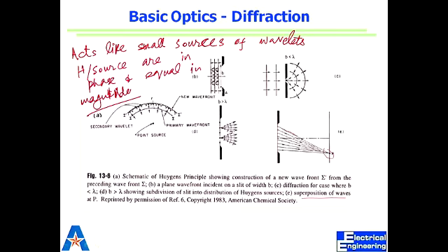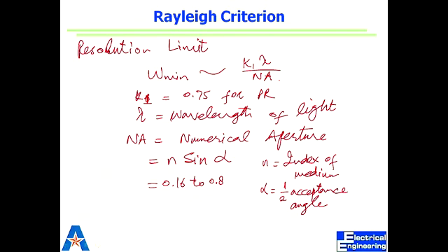The idea is that this results in specific relations that depend on the numerical aperture of the medium, because of those point sources of light. We have seen this before, right? The resolution limit, the smallest feature that can be made with the technology, depends on K1, which is a constant for a specific photoresist, the numerical aperture, and lambda. So ideally, if you want to make the resolution limit small, we should push for smaller lambda, right?